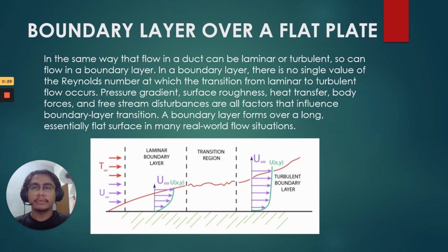A requirement for the boundary layer to be thin is that the Reynolds number of the body be large, 10^3 or more. Under this condition, the flow outside the boundary layer is essentially inviscid and plays the role of a driving mechanism for the layer.